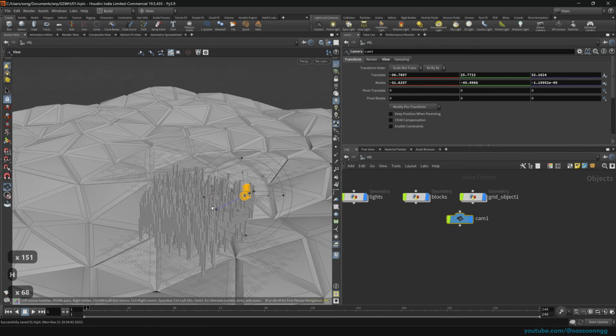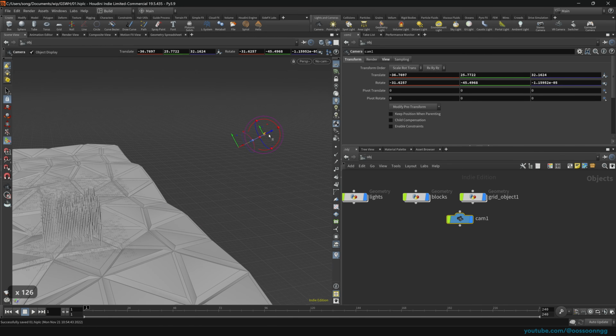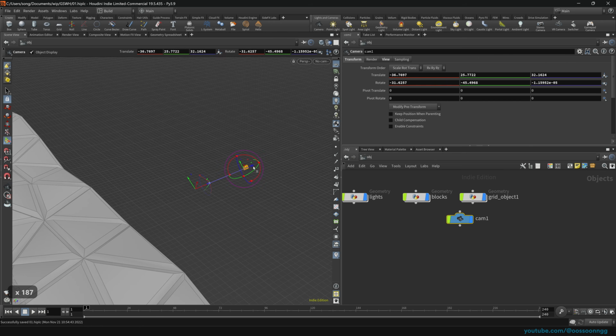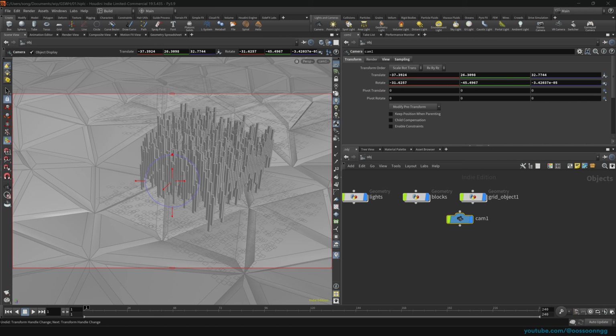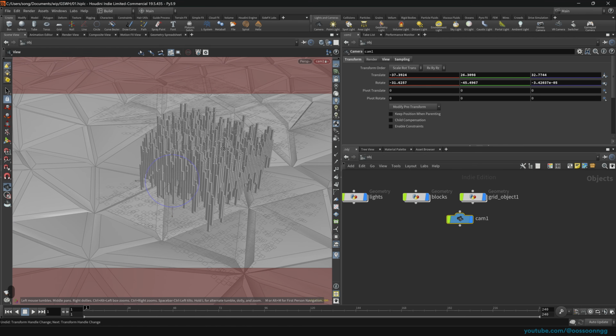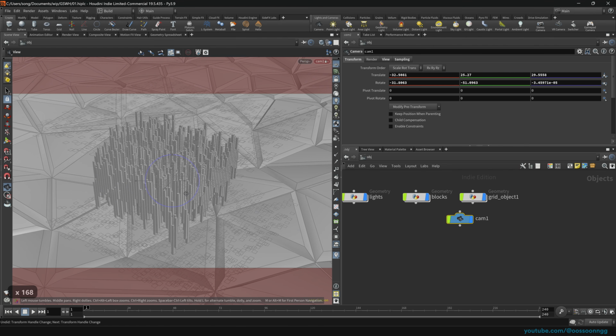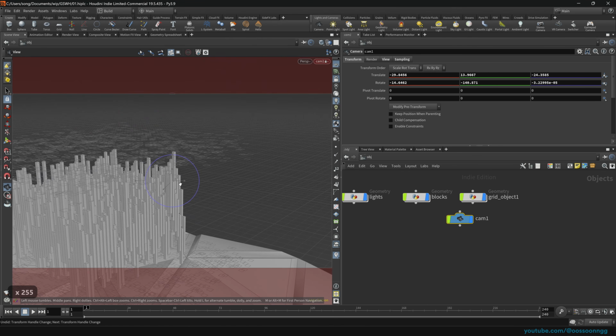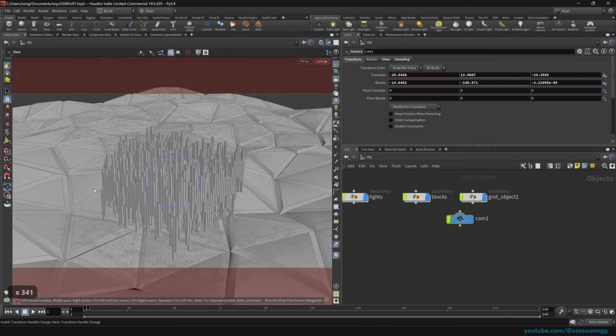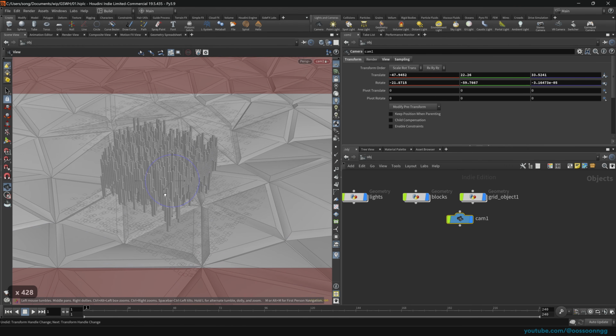It's our camera. So naturally, the super obvious way to move our camera about will be like this, you can transform it. However, there is, in my opinion, a better way. You can go here, it says no camera. We can look through camera number 1, and if we press the lock icon, however we navigate inside of our viewport will be how our camera will be positioned. So that is really, really useful.